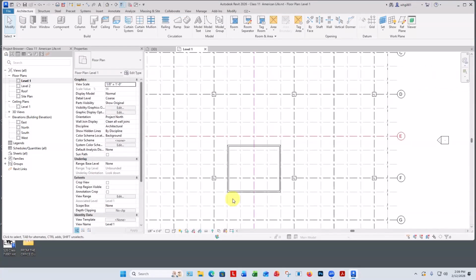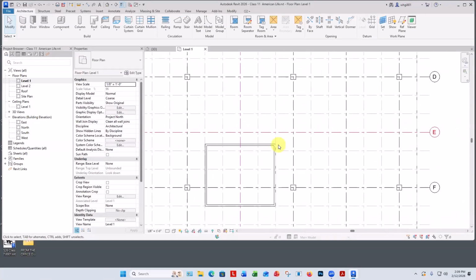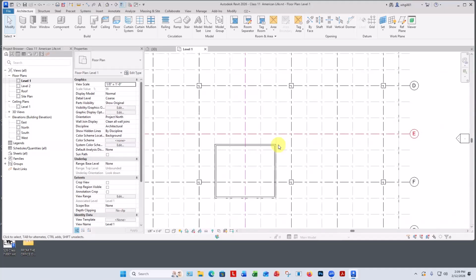We don't need them. The reason these are slightly off module here is that on the first floor, the outside of the structural wall lines up with these. By the time it's narrowed coming up, it's not doing that anymore. So somebody's got to take up the slack.